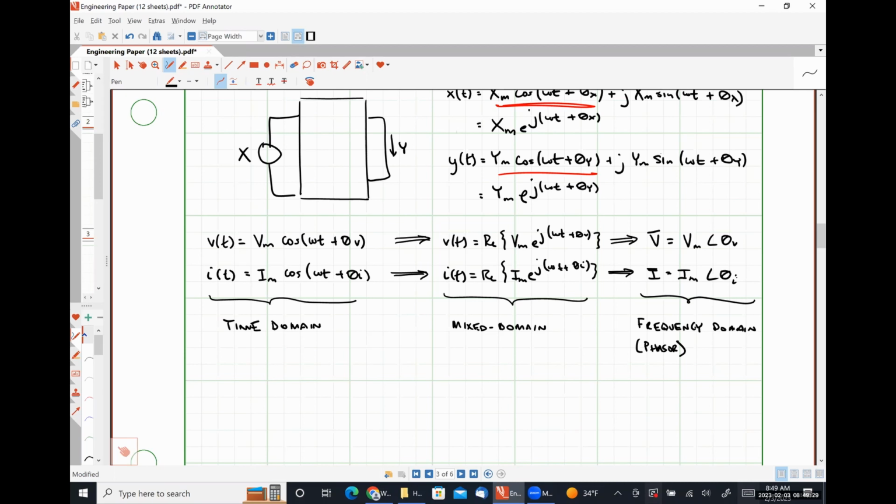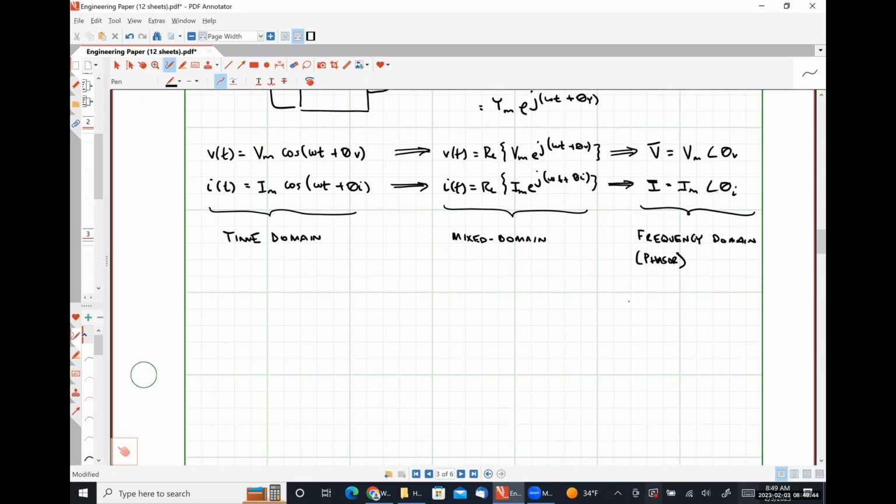In order to get the phasor representation of any voltage or current signal, the time domain representation of that signal has to be with a cosine reference, okay? So, excuse me. Let's say that I have VA of t is equal to 10 cosine 15t plus 83 degrees volts. What would the phasor representation of this be?